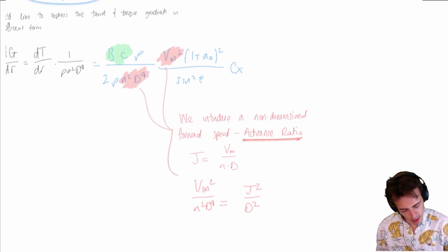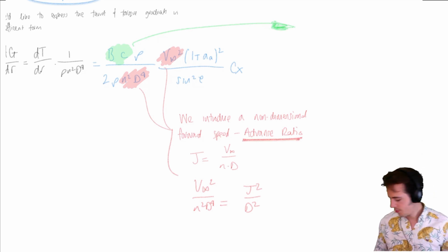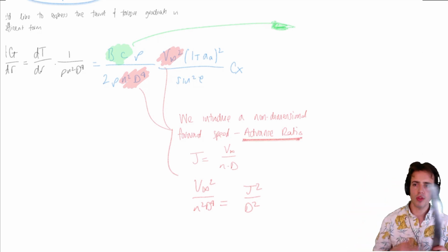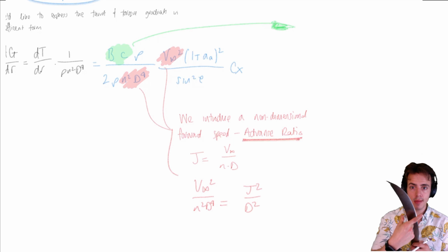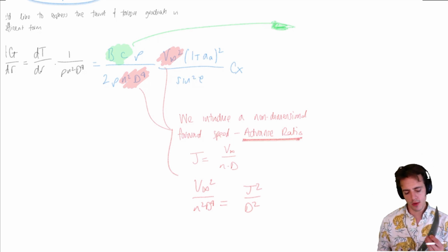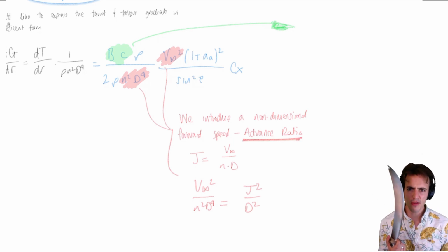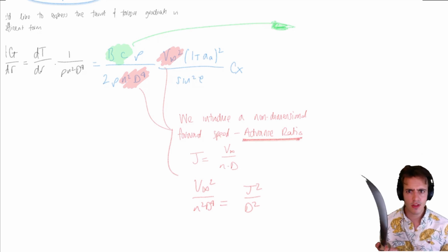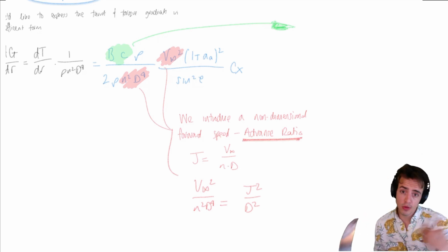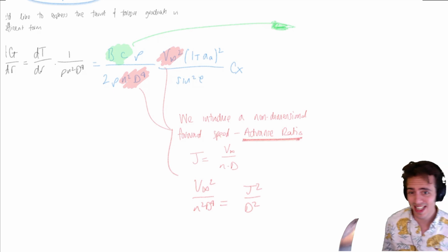So then we've got these two terms here. We've got the number of blades and we've got the local chord. We can appreciate here that we've got something that's going to get bigger when we've got more blades, and if they are fatter blades, if they've got a bigger chord. So that's effectively saying if we had a lot of these, then we're trying to work out how much of the disk area is made up by blades. How much of it is solid, we could say. So this introduces a parameter that we call solidity.